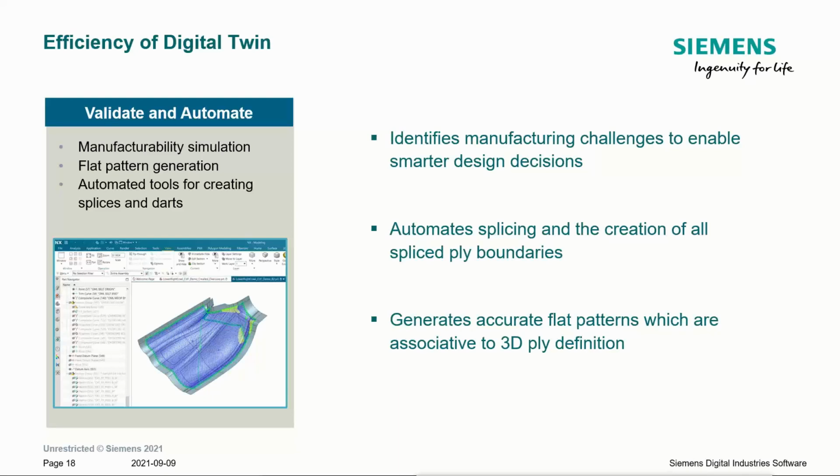As Leigh mentioned, you don't want to be doing design on the tool. You don't want to have different people interpreting it differently, adding excess material or putting darts in different areas. If you hit that layup start point, smooth it the way it was designed in Fibersim, the ply is going to go to the extent of the boundary and lay up without issue. This has been proven for many years.